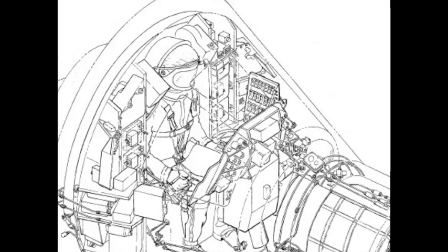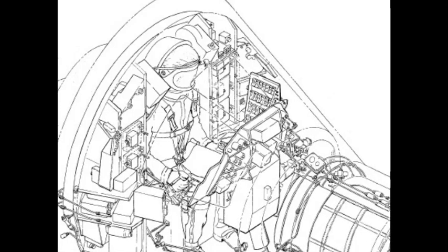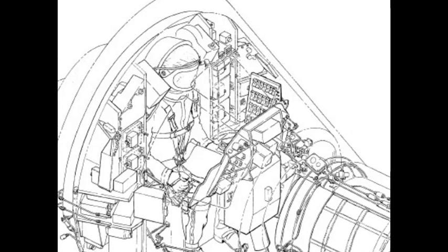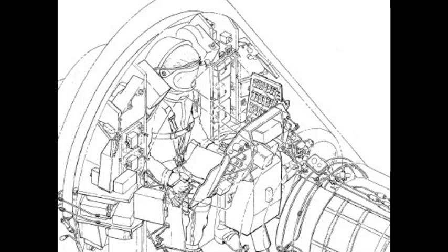2.9. The small pressure bulkhead internally separates the cabin pressurized area from the recovery system compartment and structurally supports the aft conical section. A sealed escape hatch, figure 2.4, internally actuated, is provided in the small pressure bulkhead to enable the astronaut's exit following capsule landing.